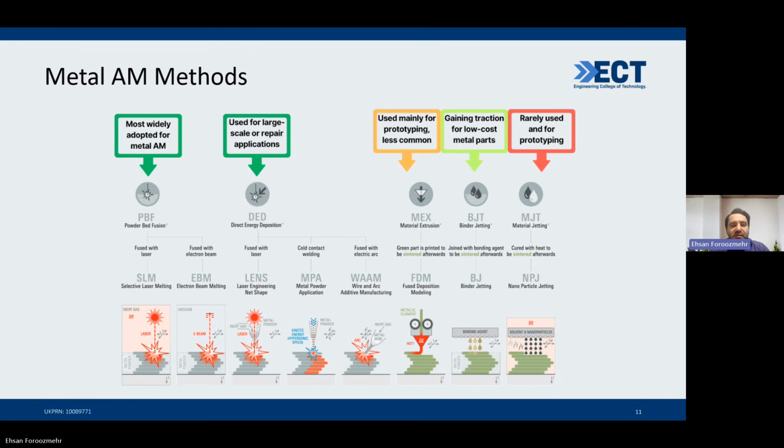What you do is, like FDM technology, you have a filament that is melted to make the part, and that filament has metal particles in it. Once the part is printed, we call it a green part. That green part has to go through a sequence of post-processing to increase the strength and remove the excess material. As a result, there is a lot of shrinkage, 20, 30, 40%, until we get to a semi-solid material.